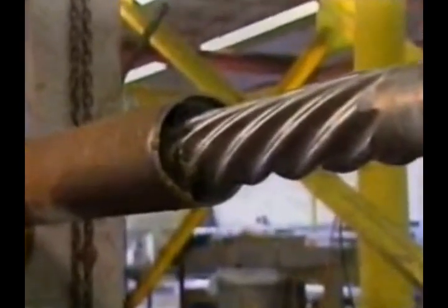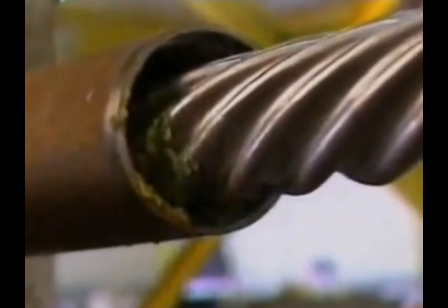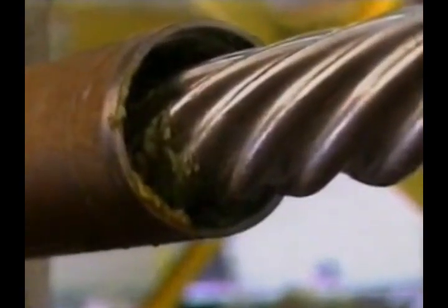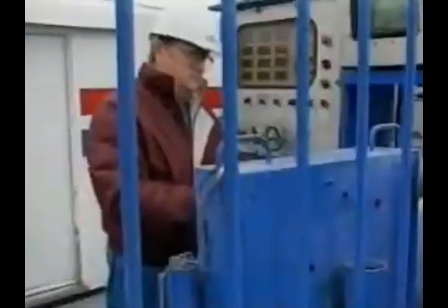It enables us to initiate deflection simply by incorporating a bent housing into the motor or by using a bent sub or eccentric stabilizer. The bent housing shown here is adjustable, thus providing even greater flexibility and directional control. Conversely, to keep a straight well course in crooked hole formations, we can run the motor without a bent housing or bent sub.